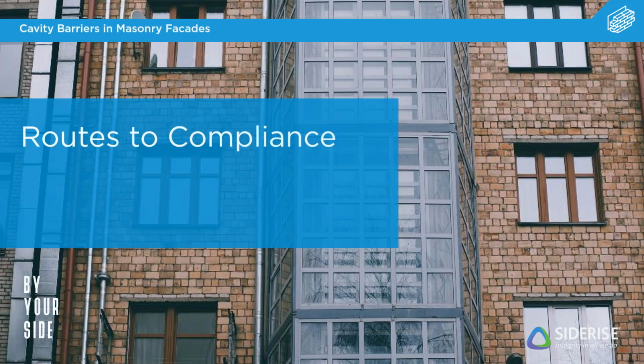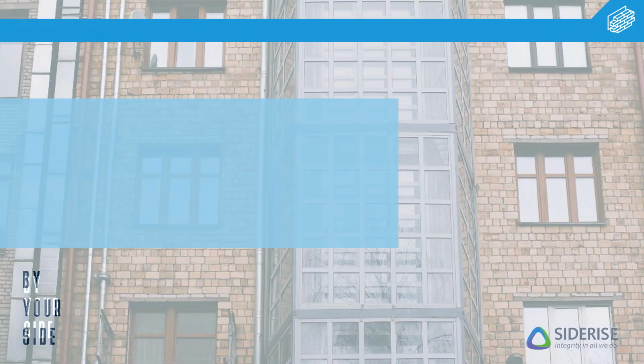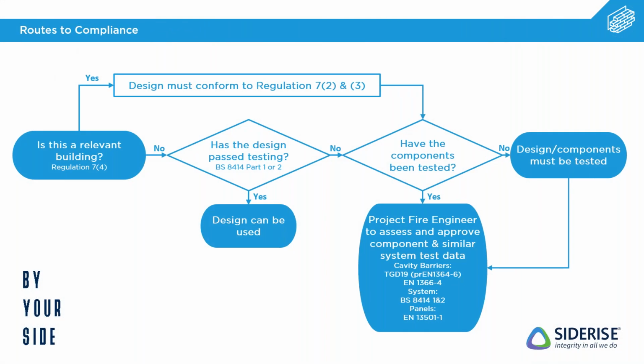So now getting on to the actual routes to compliance, some of the important bits. I mentioned before that Regulation 7 has had an effect on routes to compliance and specifically large-scale testing. It's something that's not typically as common within masonry applications, but you can actually do large-scale system tests such as the BS 8414 test with a masonry facade.